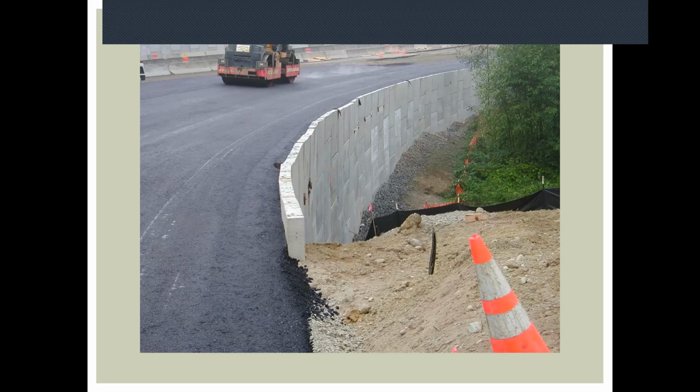Like here, the curbs aren't in. So water is going to go screaming down the asphalt. It's going to drain down this dirt ditch area. And that happens to be a wetland to the top right. So, see these things. It's not raining yet. Have the contractor put in some temporary curbing, sandbags, or something like that.